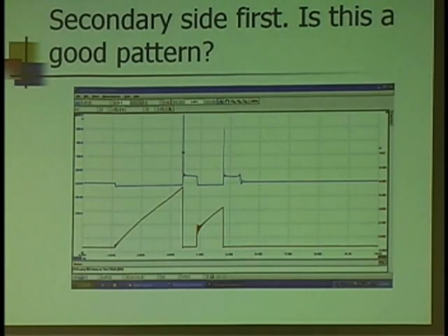Let's just take a look at the pattern that we're looking at here first. That looks kind of weird. Is that a normal pattern? Is that a Ford? It's a multi-strike ignition. What does Ford do at idle on a lot of their models? They actually fire the plug 2 or 3 times really quick. And that's what you're seeing here. First time I saw it, I was like, what the hell is that? Me also. Yeah.